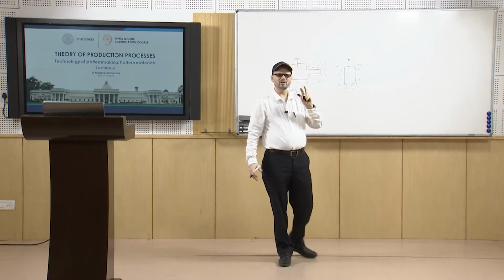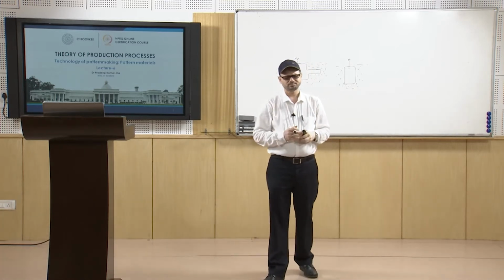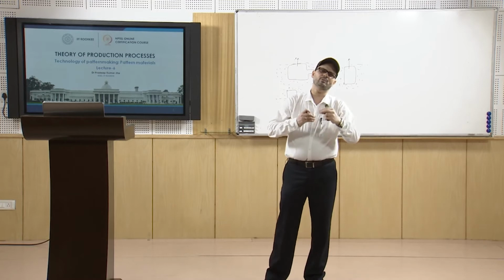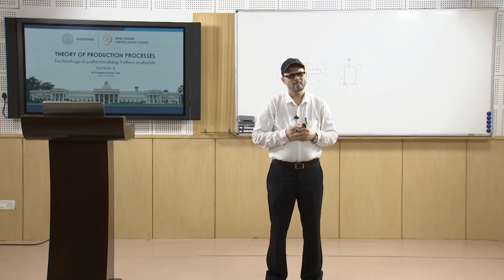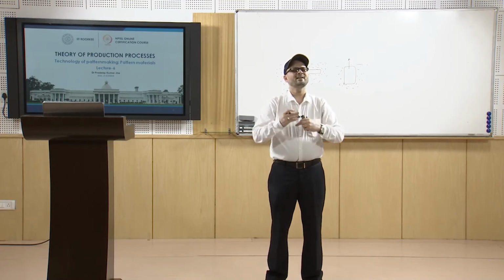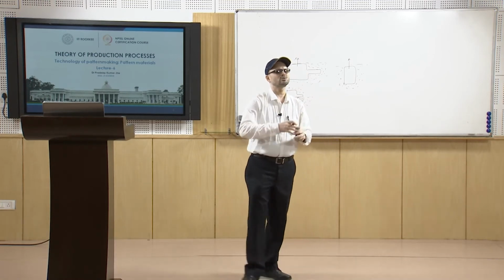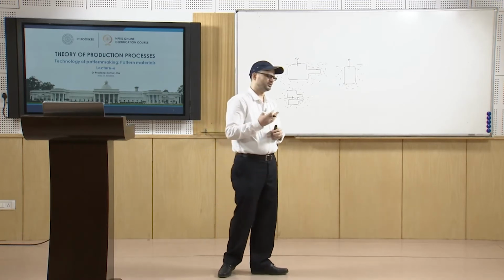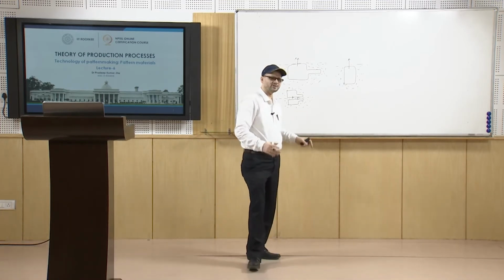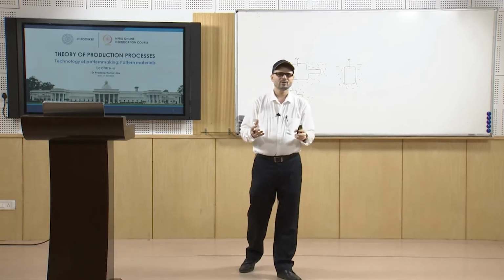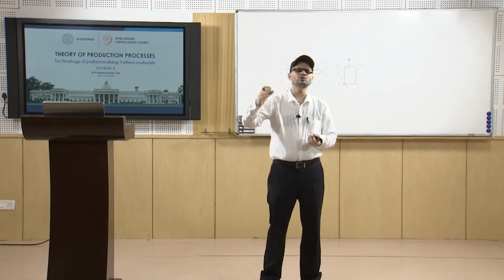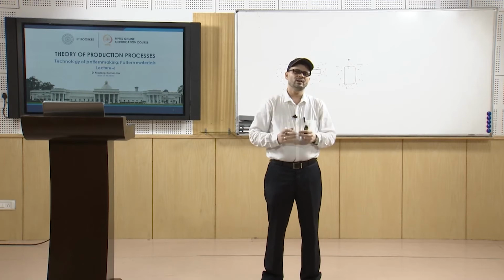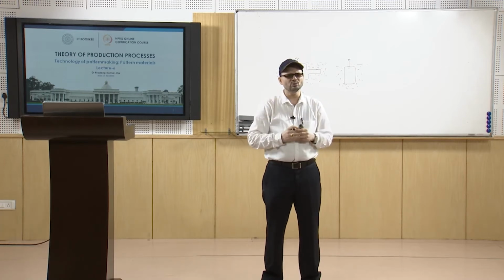So, wood is normally used, but slowly, depending upon the requirement of surface finish, or wood not being available, there are many disadvantages also, like storing of the wood for a long time. Many of the woods which are available do not remain dimensionally stable, and it matters how long you have to use the wood and in what atmosphere it is going to be used.